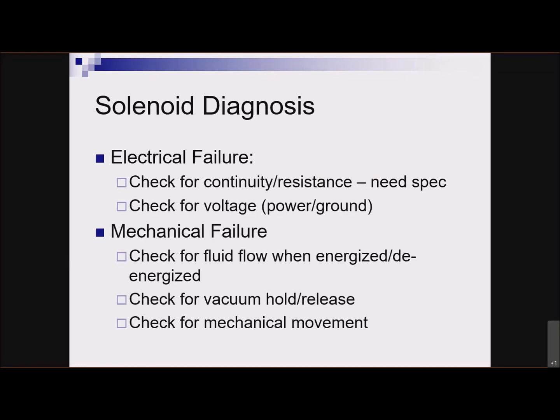Now what you do is you go to your scan tool, go to the output controls, command that solenoid on, and watch for the light to light. If that light lights, then you know the control circuit is working fine and the problem is in the solenoid itself. If that light does not light, then you don't think it's the solenoid, you think there's a problem with the control circuit. So that's a way to check the circuit.